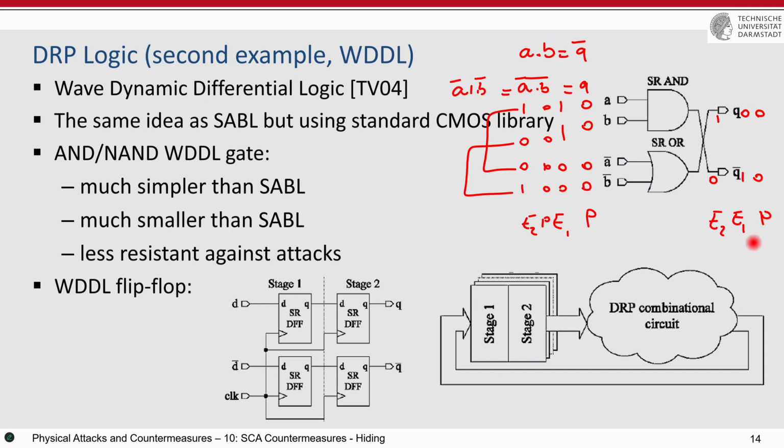What you see here is, in general, how the circuit is built. Now in dual rail logic, or DRP circuits, dual rail pre-charge logic, here is a combinational circuit which is fully built by the WDDL gates, like here the AND gate. What you should also consider, which I did not explain, is what the inverter is in these circuits.